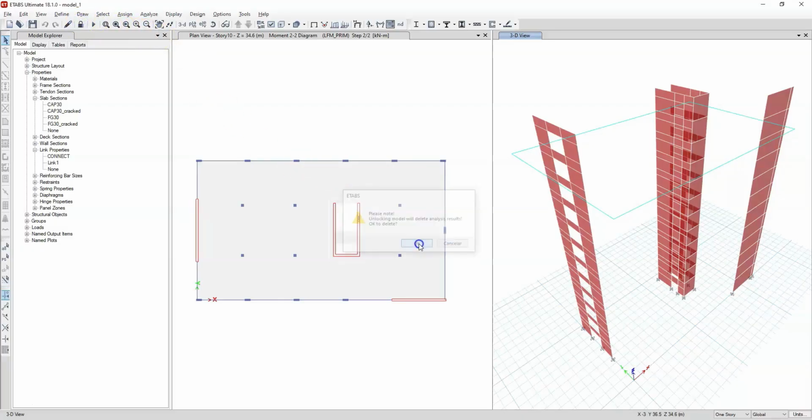We must consider how to define the action we will use for the comparison. It should be a horizontal action, preferably seismic. Why not use a response spectrum analysis? The truth is that we are talking about two structures with totally different stiffness configurations. One we call crack stiffness, including primary and secondary elements, and the other being only the primary structure. If we used a response spectrum, it would be based on modal analyses reporting different stiffnesses, different fundamental periods, different frequencies, and different accelerations on the spectrum. We wouldn't truly be comparing two actions with the exact same magnitude and distribution.